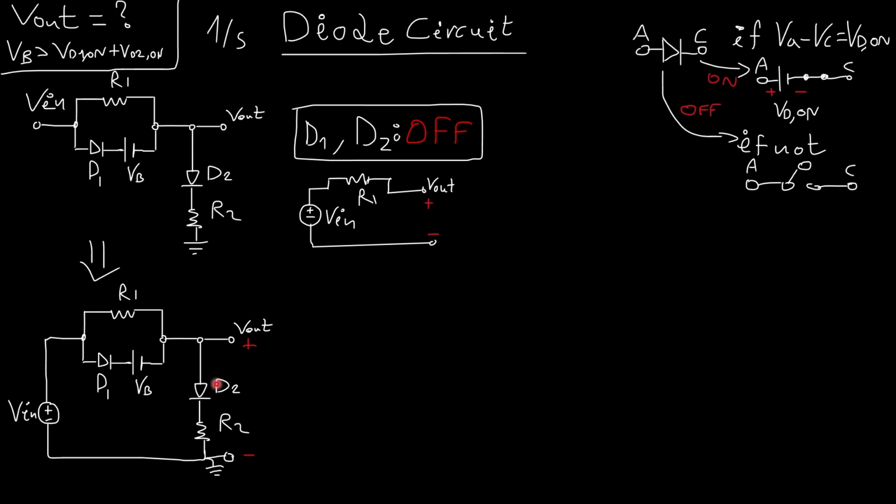So this circuit will be open, this circuit will be open. So I would have nothing but a resistor between the output and the inputs, and I would have no closed circuit, so there would be no current, so the output would be the same as the inputs. Right, no current, no voltage drop here. Alright, that was easy.